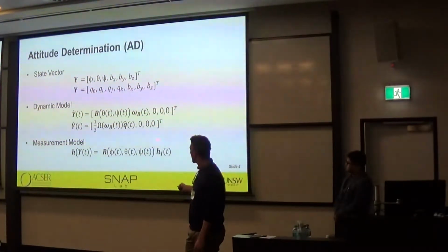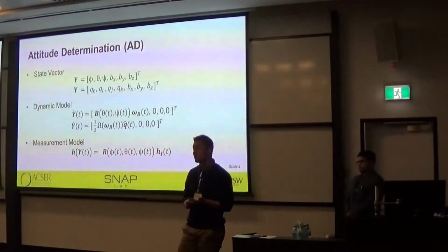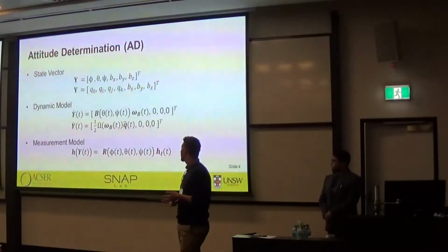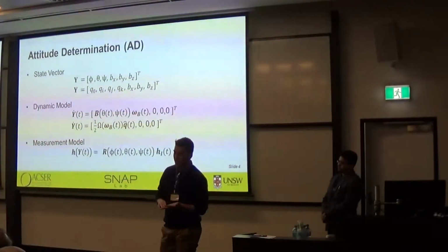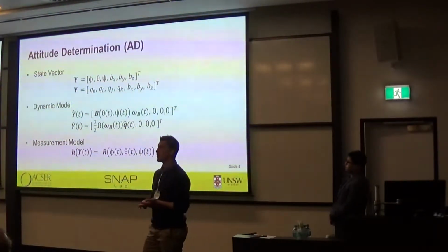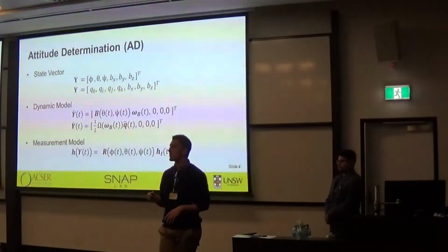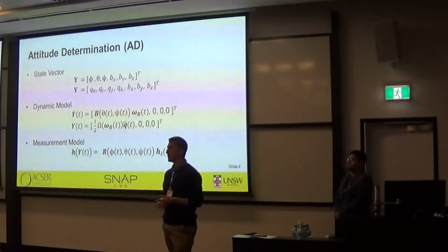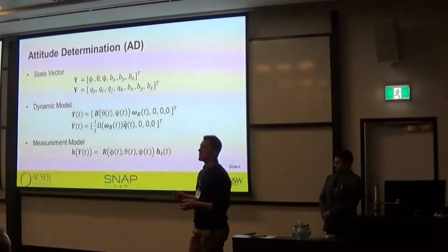And these inertial vectors are calculated based on that world magnetic model in ECO, or you can use any type of magnetic model that you like, which then results in the requirement that the attitude determination system needs a position fix. So then you've got all of these other things that Matt was talking about yesterday, where they use their GPS and they have an orbit determination algorithm while we use an orbit propagator.